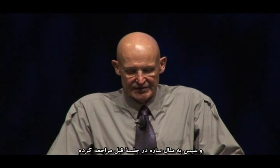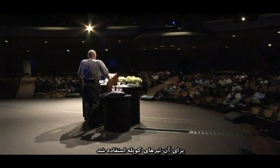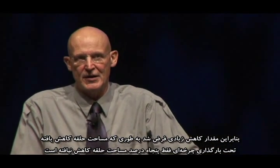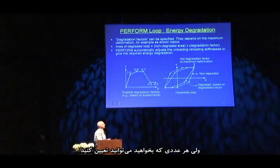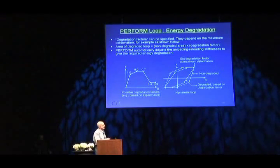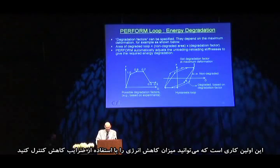I was talking to somebody earlier about the coupling beams and the example structure we looked at in the last session, and what was used for those coupling beams was a factor of 0.15 for basically all displacements. So there was a lot of degradation assumed, that the area of the degraded loop under cyclic loading was only 15% of the area of the non-degraded loop. But you can specify any numbers you like if you have experimental data available. It's not too difficult to pick some reasonable numbers. That's the first thing you can do, you can control the amount of energy degradation using degradation factors.